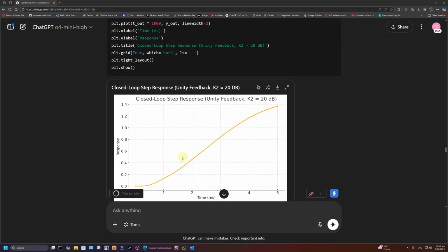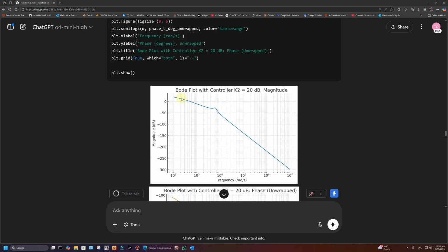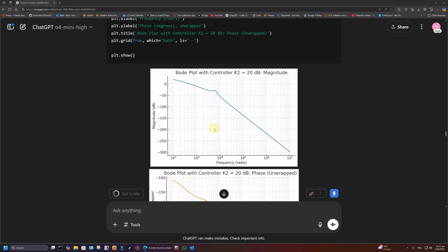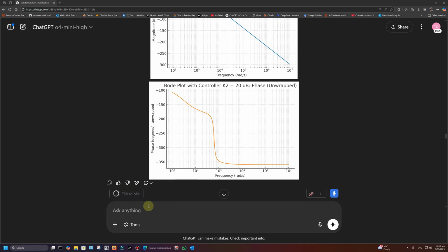So if we go to the Bode plot here, what you can do is add an integrator at low frequencies, and then put a phase advance in here, and push the bandwidth up so that this resonance must be below 0 dB. You can read my book for the details, but not everybody wants to design using lag-lead controllers. A lot of people in industry just use PID controllers, and you should get approximately the same answer.